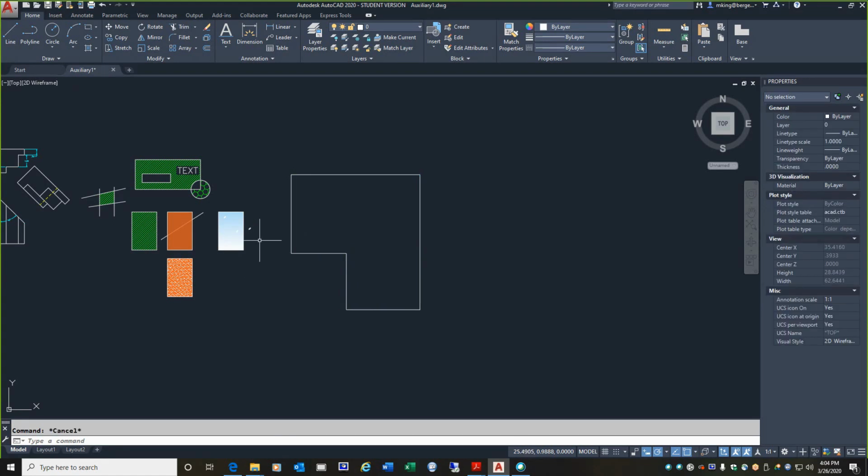Now, let's see some of the benefits of this. Number one is, if this were the outline of a floor plan, I could just use the offset command and offset that inward for the inside wall, whatever the thickness of the wall is. Okay? So let's do that. So let's go to the offset button here. Specify offset distance. We don't select anything yet. And let's say, well, this is not a real size floor plan.